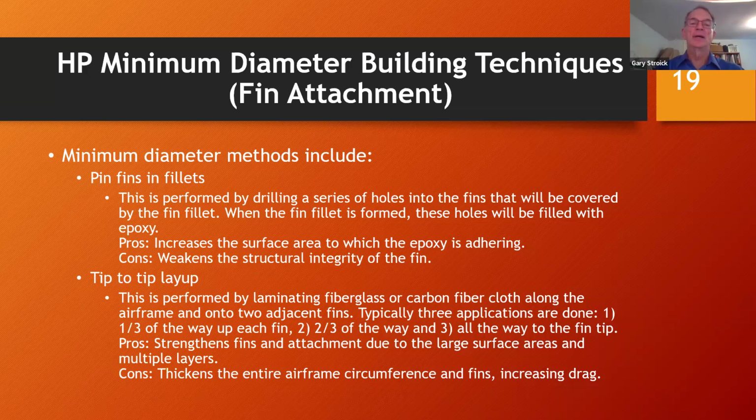So that's the idea there. Depending on the epoxies you use and so on, there are some other additions that you could use. You could put in those holes, or in the epoxy itself, chopped fiberglass or carbon fiber or other materials to help strengthen the epoxy, and also strengthen the epoxy through those holes to hold it in place. So there's a lot of different modifications that you can consider there.